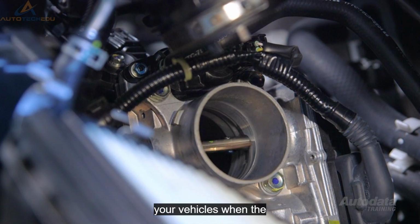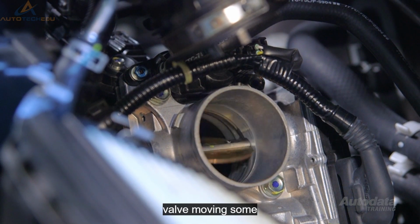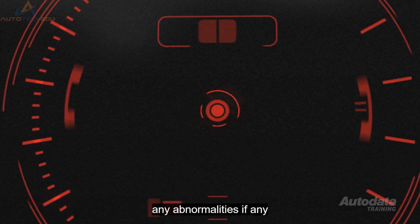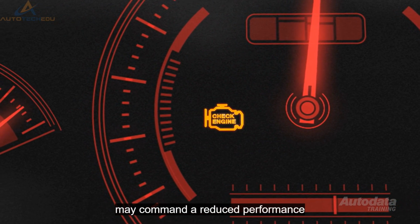On some newer vehicles, when the ignition is first switched on, you may hear the throttle valve moving. Some manufacturers use this as a self-test procedure. The ECM monitors the TPS voltages for any abnormalities. If any fault is found, the MIL may illuminate and the ECM may command a reduced performance mode.